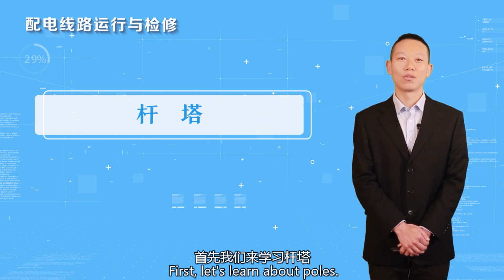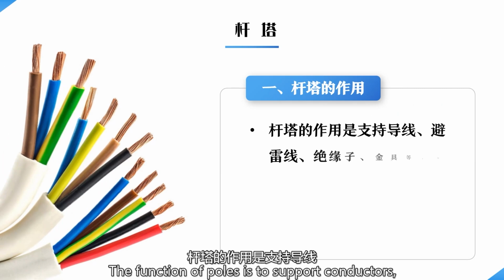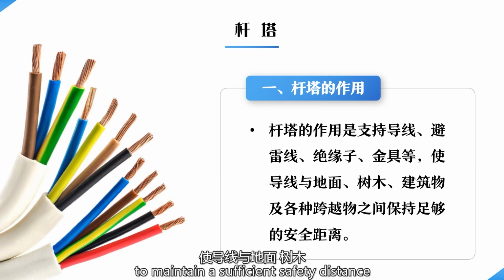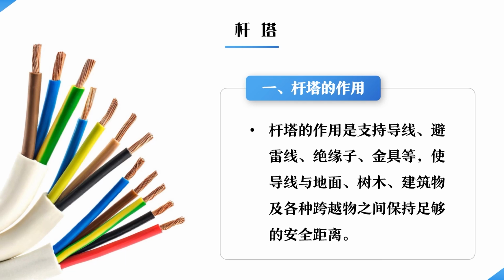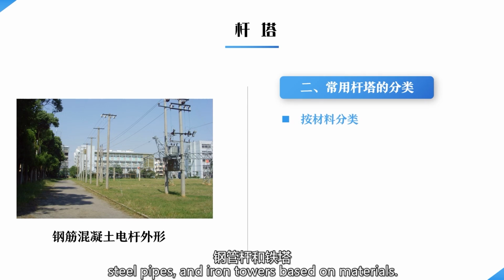First, let's learn about poles. The function of poles is to support conductors, ground wires, insulators, fittings, etc., to maintain a sufficient safety distance between conductors and the ground, trees, buildings, and various crossing objects. Poles can be divided into cement poles, steel pipes, and iron tower based on materials.